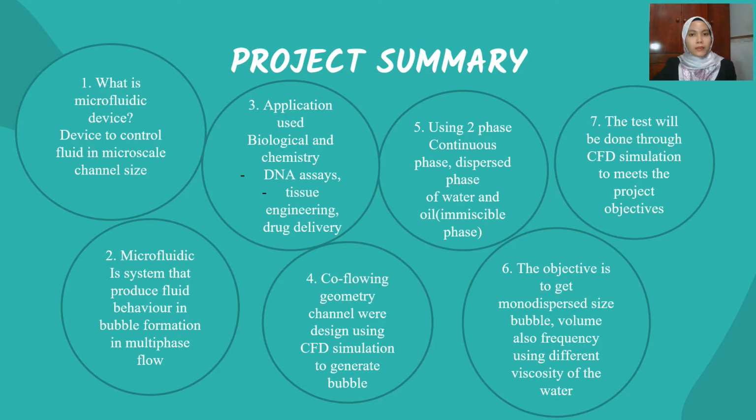This bubble is produced by a microfluidic device that must deal with multi-phase flow. This multi-phase flow consists of two phases that use two different fluids, which are the continuous phase and the dispersed phase. In order to become multi-phase flow, the two phases must be immiscible liquids, which means the fluids cannot mix together to create an emulsion between two different fluids such as water and oil, so that the bubble will be produced.